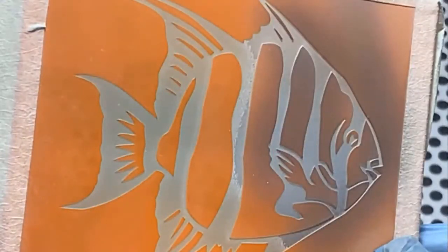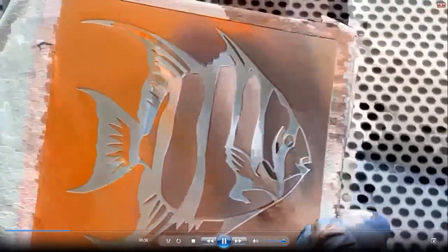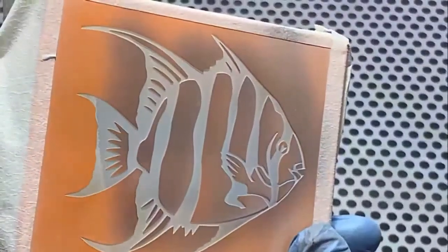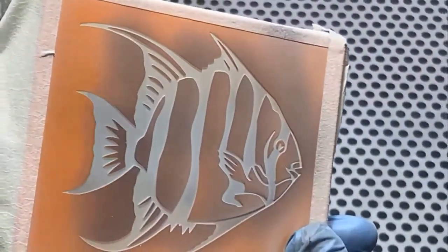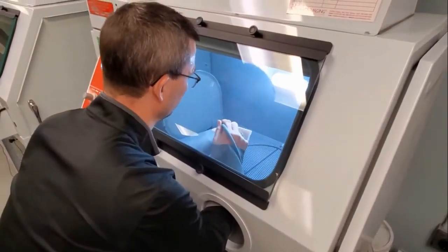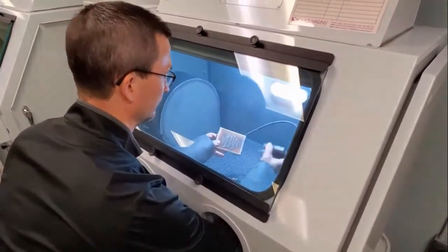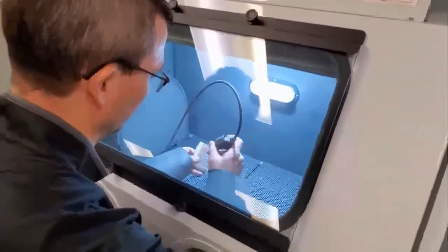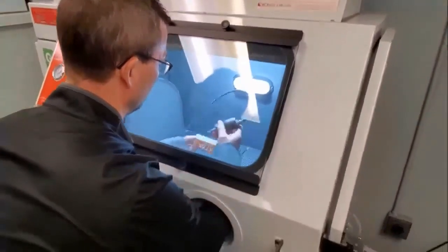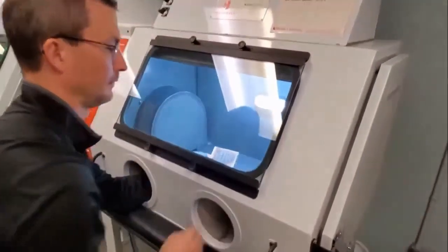As Dave mentioned, you can go all the way through the membrane, or you can leave some behind. Sand carving, the abrasive is going to penetrate through even up to a mil of Blazer Orange material. So again, it's up to you as far as what your technique goes. At the end of my sand carving, I use an air gun to remove any of the dust, any of the abrasive, so it gets reclaimed in our machine.